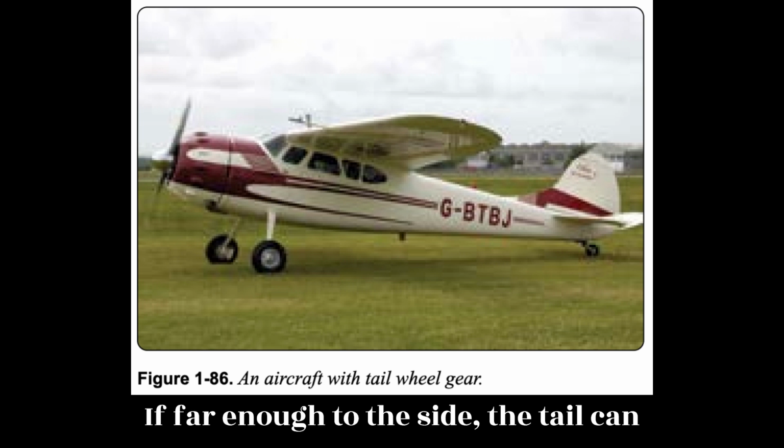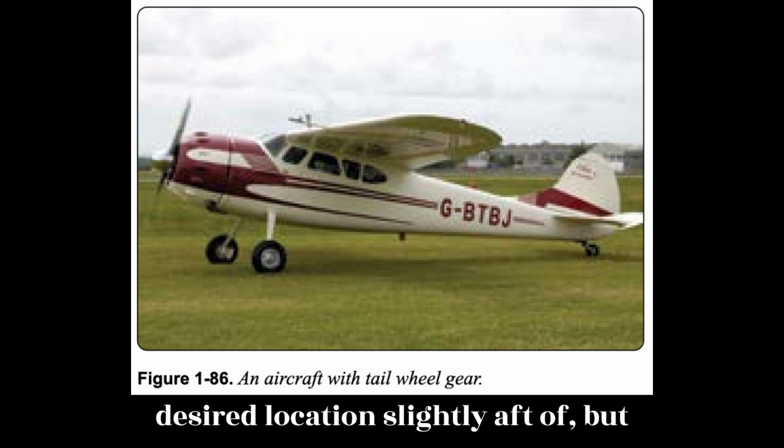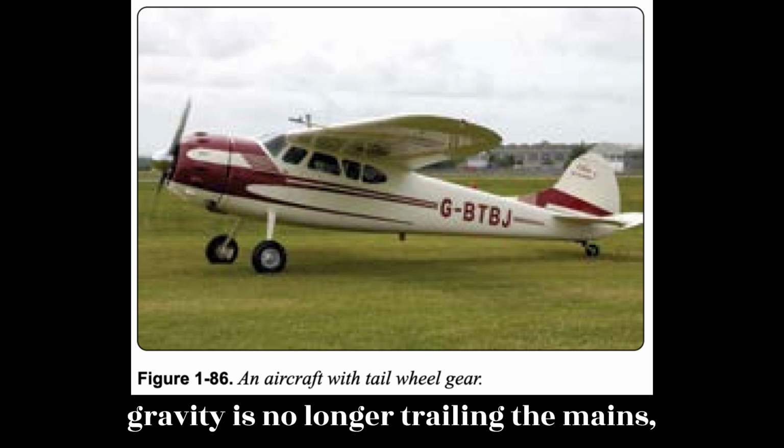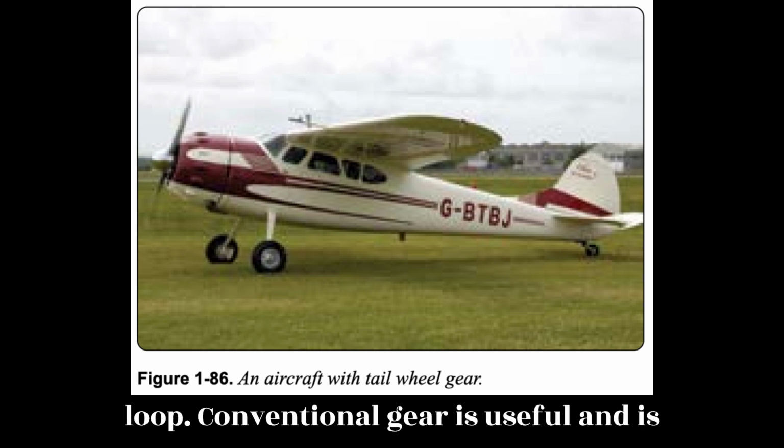If far enough to the side, the tail can pull the center of gravity out from its desired location slightly aft of but between the main gear. Once the center of gravity is no longer trailing the mains, the tail of the aircraft freely pivots around the main wheels, causing the ground loop.